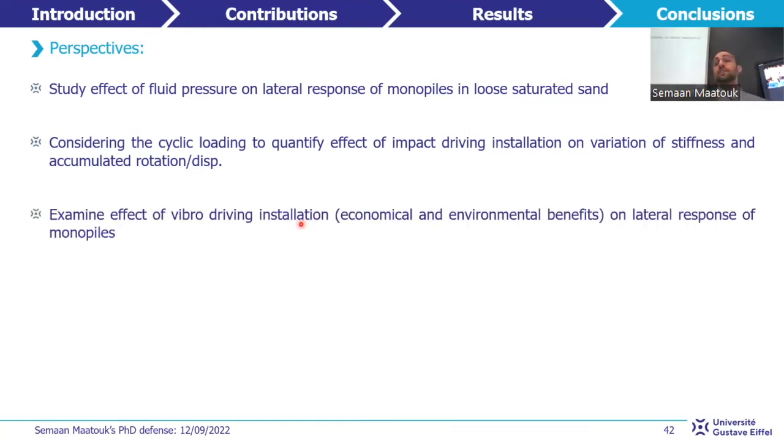In addition, the new quieter and faster vibro-driving technique is now attracting a lot of interest in the offshore industry. Therefore, it would be worthwhile to quantify the impact of the installation on the horizontal behavior. And finally, developing a 3D FEM model with the consideration of the impact driving installation should be a direction to better understand and quantify the horizontal response of today's large monopiles of about 10 meters in diameter.